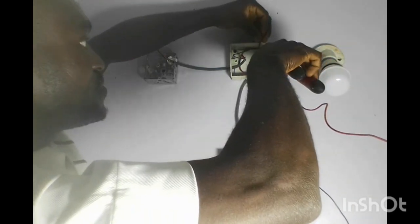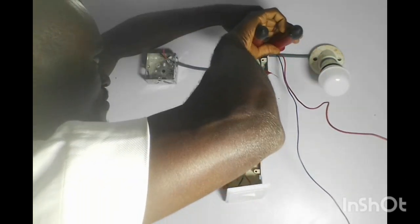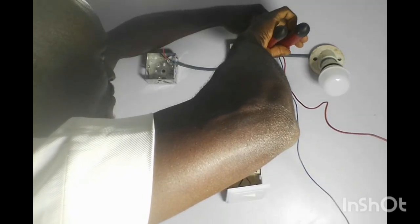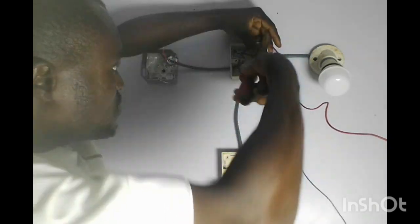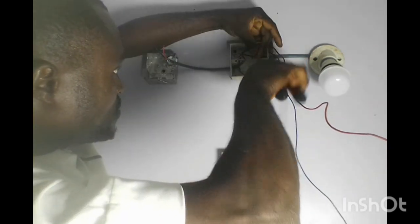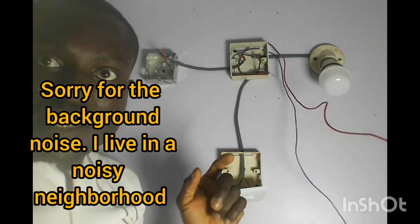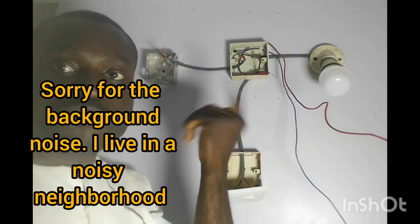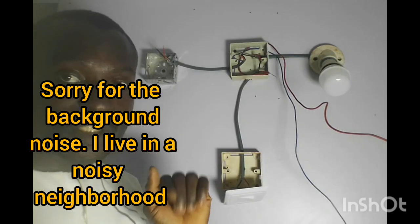So I'm going to connect this. So as you can see, I've connected the black wire coming from the switch with the live wire from the load. So yeah, that connection is done.